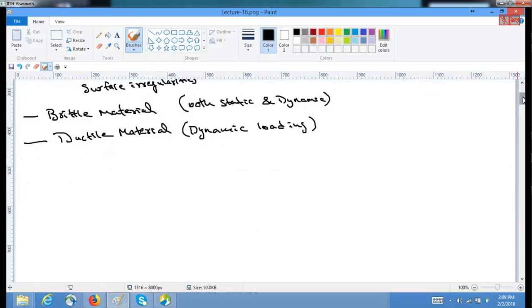And we have seen some simple machine elements which are subjected to different kinds of stress concentrations. Sometimes we try to mitigate it through manufacturing means, like drilling a hole, giving a fillet, rounding off, or removing some material.